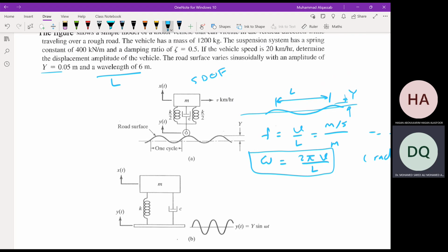We know that the car has 4 tires, but when you neglect the rotation of the car and assume only vertical vibration, which is bouncing, and treat the tires as rigid, it becomes a single degree of freedom system. Okay, we will come back to this example next time,